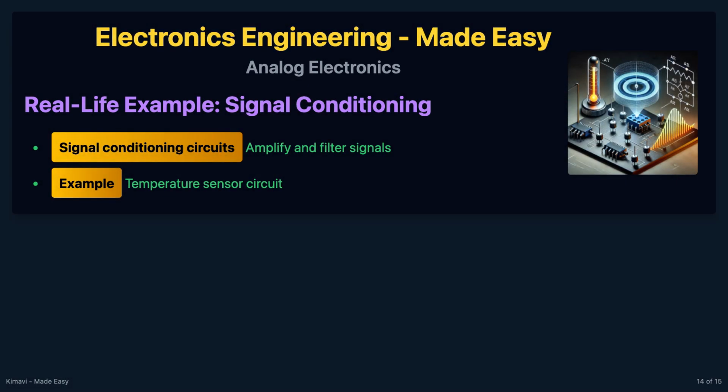Operational amplifiers are used in signal conditioning circuits to amplify and filter signals before they are processed by other components. For instance, in a temperature sensor circuit, the small voltage output from the sensor can be amplified by an op-amp to a level suitable for analog to digital conversion.